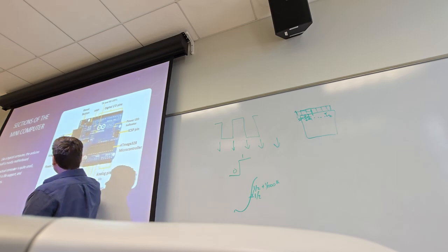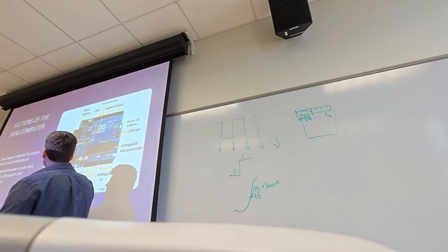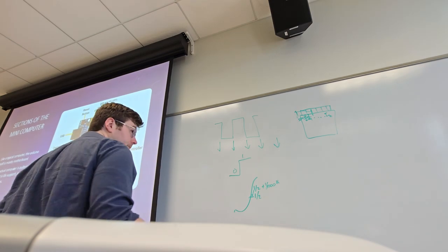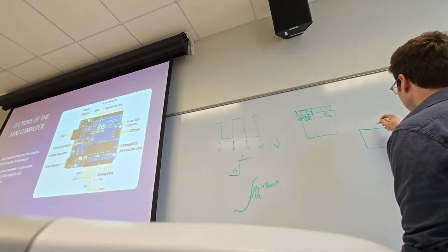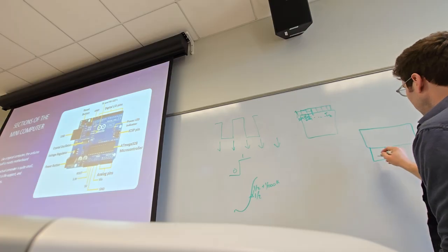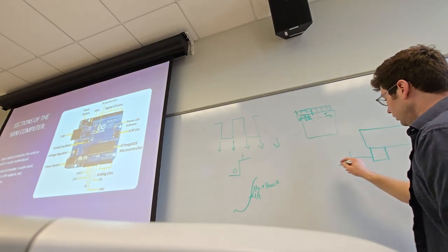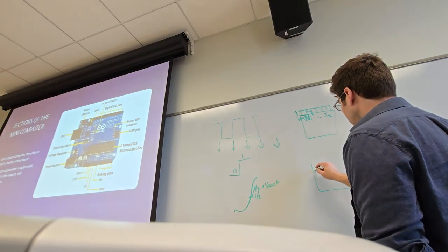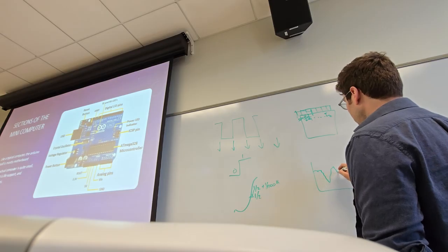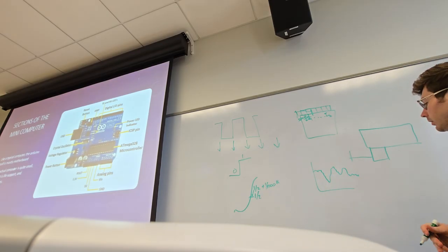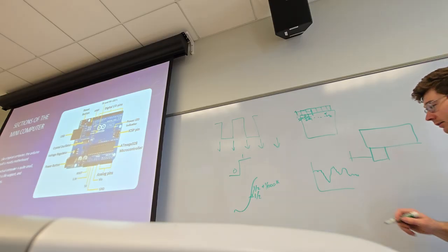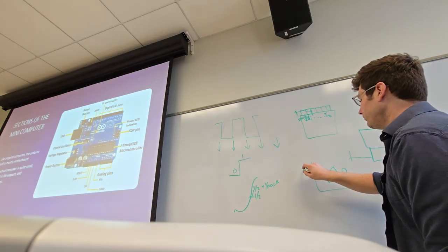Because this chip right here is the voltage regulator. Its whole job, it's essentially a 3-pin device, is that on one pin, it takes in noisy, unstable input voltage from a battery, from a power supply, from a wall wart, whatever, that might be way higher than 5 volts.